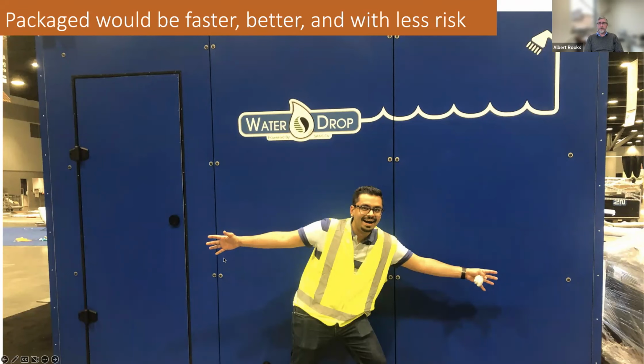Because as you look at designs as they come out today, there's a rather specific mechanical plan and plumbing plan, and all the piping has to be in the right place. You have to use the right check valves and make sure the heat pumps are not able to overcome the pressure of a spring check valve. And there are things you have to learn along the way.